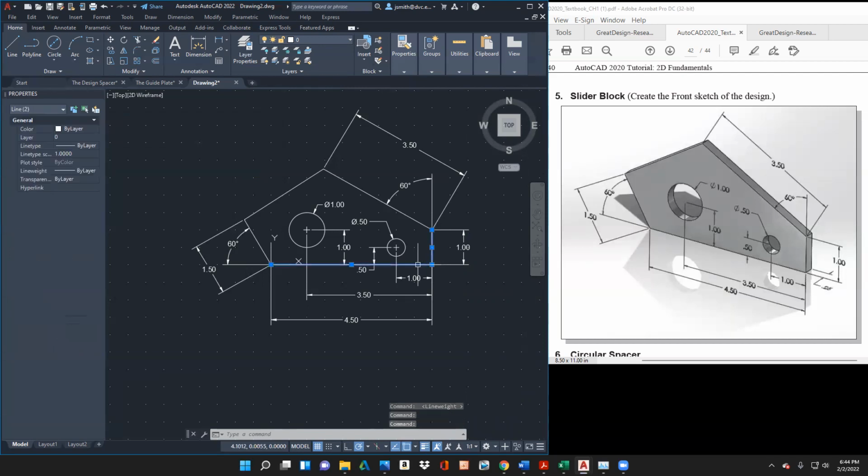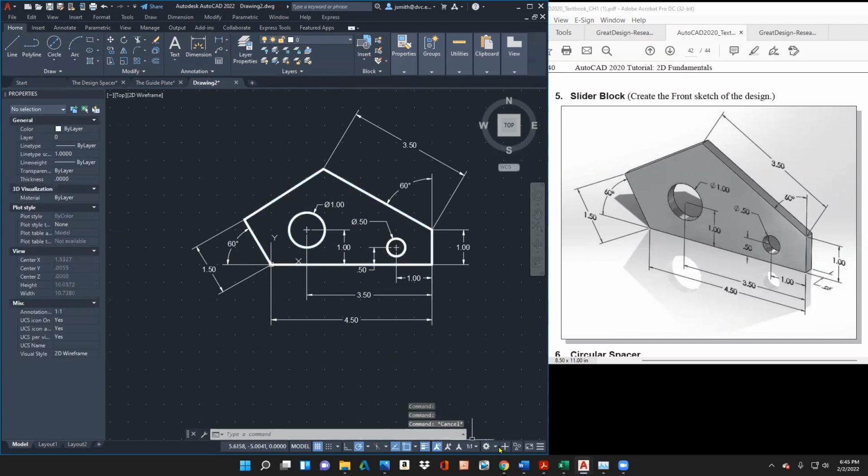I'm going to very carefully go around and select, I think there's 5 lines here. And I also need to select the part line, the center. So the outside and then the circle. Then on my properties, I'll go to line weight. I'm going to select 0.50, right? And if you're not seeing it when you change it, that's because this has been turned off.